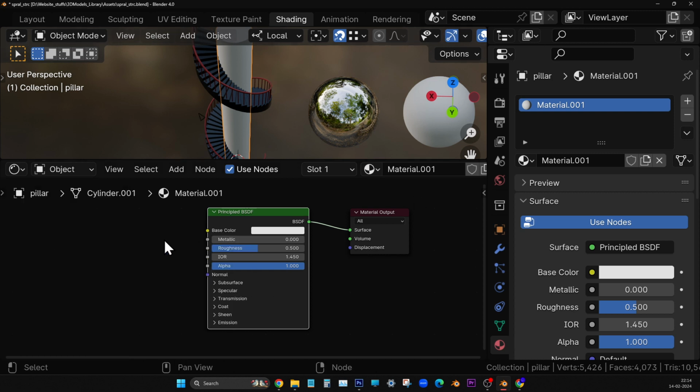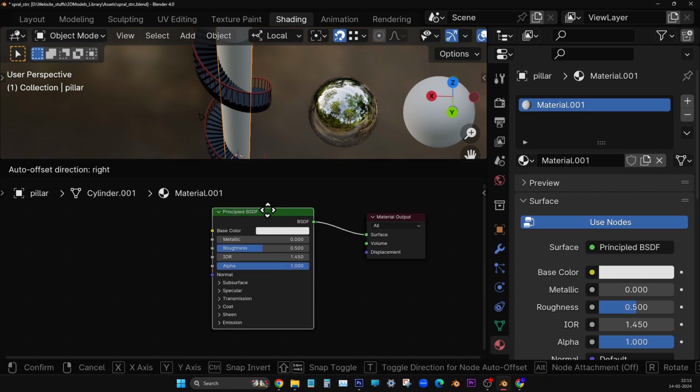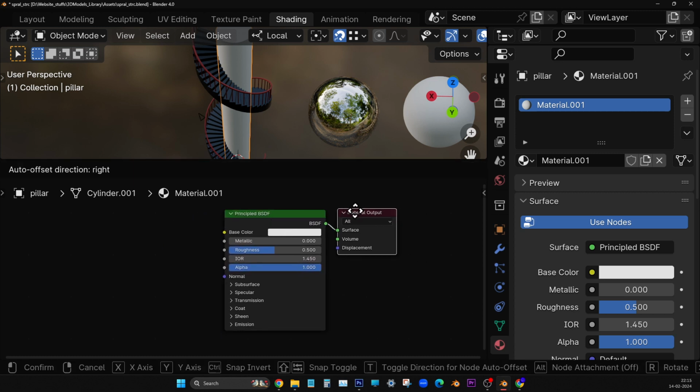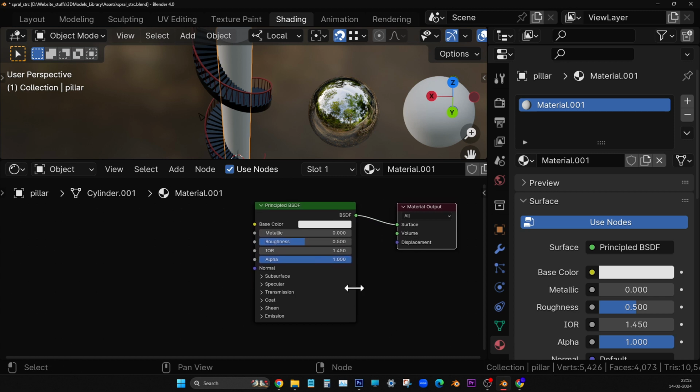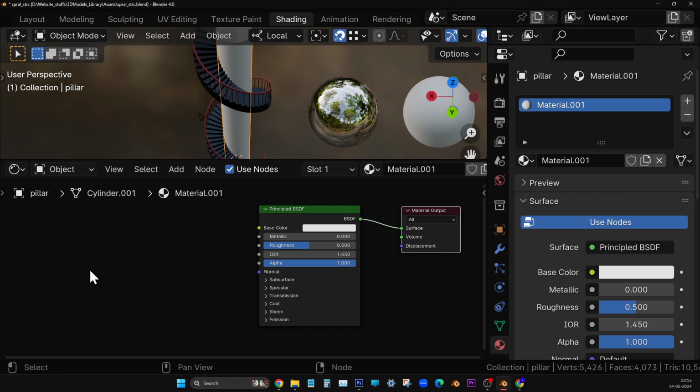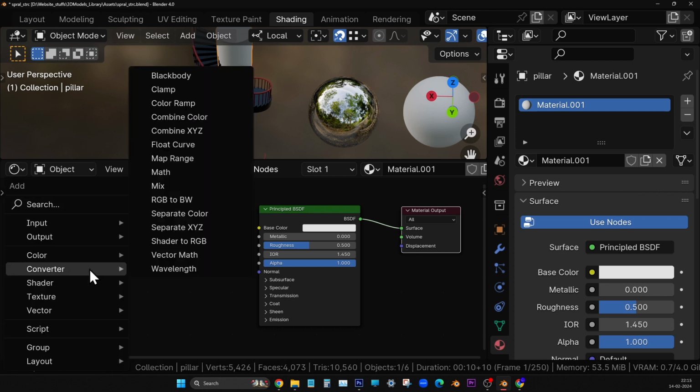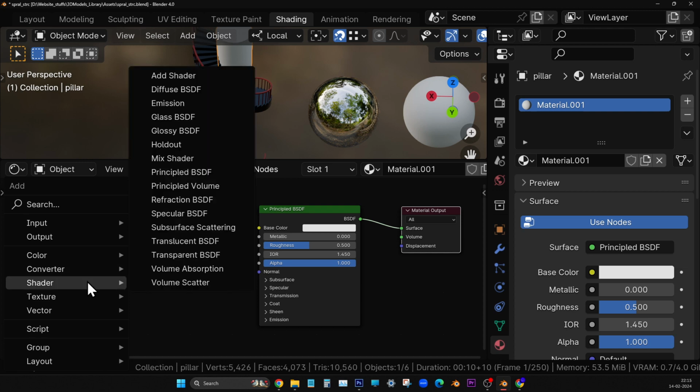I'm in shading module. I'm inside this shading nodes panel. My cursor is inside the shading nodes panel. You can see the shaders, principled BSDF, material output. All those nodes are there hanging in the shader nodes panel. Now I'm pressing Shift A. It will show a panel. In that panel, I'm looking for the checker texture.